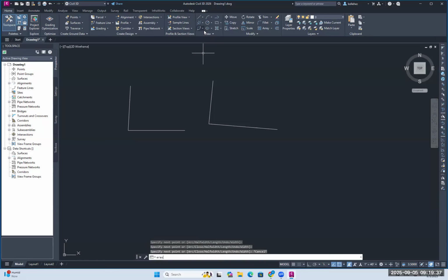I'm going to show you something with the erase feature. So if I draw just regular lines, it treats each line like its own segment. If I draw a P-line, it treats it as a continuous segment. That can be useful in some cases. So knowing the difference is important. If I can't actually select the object, another thing I can do is draw a box around it and remove it from there. So I am going to take you through my drawing of Markel Hall very quickly.